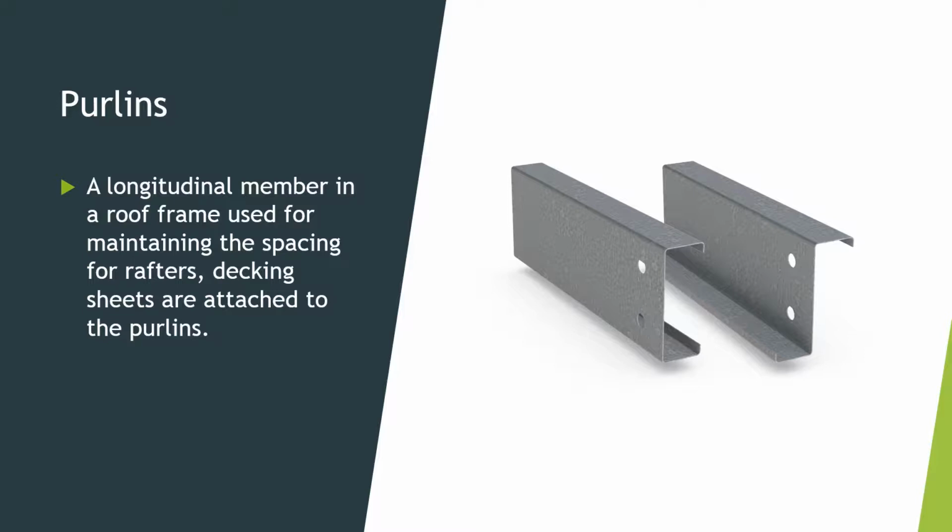So we don't need to look too further. Here's your purlins. So you got a C shape and a Z shape. So they can come in either or, and they're using the roof. So see where those holes sit? There's going to be sag rods also go through here, so it's going to keep everything nice and straight and prevent any sag in that roof that we're gonna build. So that's where the C channel comes in there in the C shape, and then we have the Z shape, and these are known as purlins.